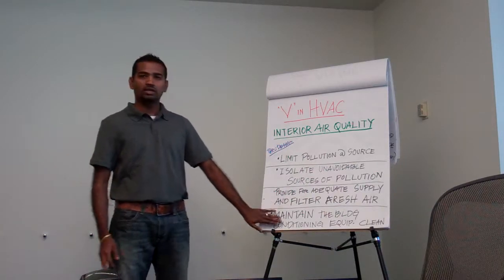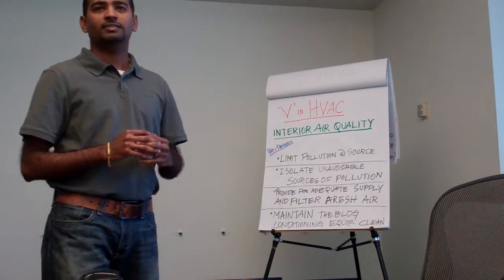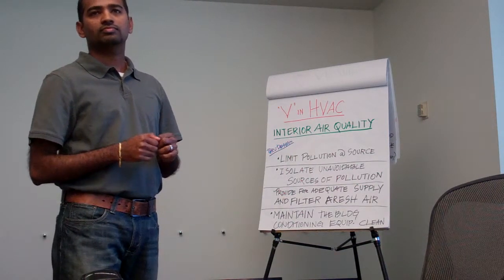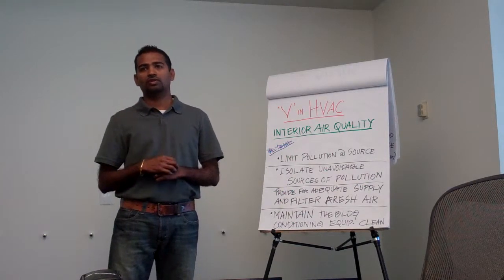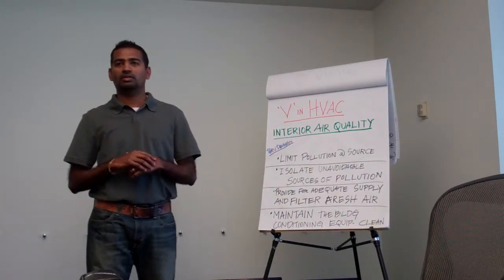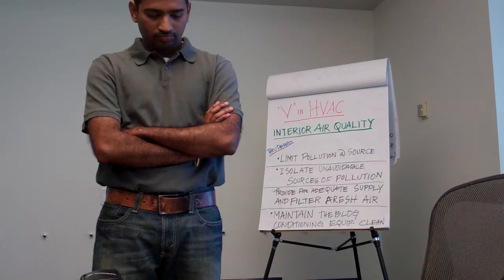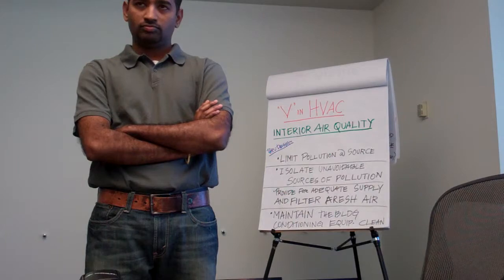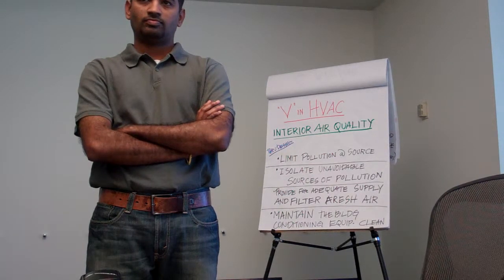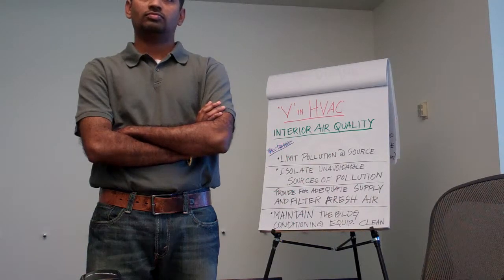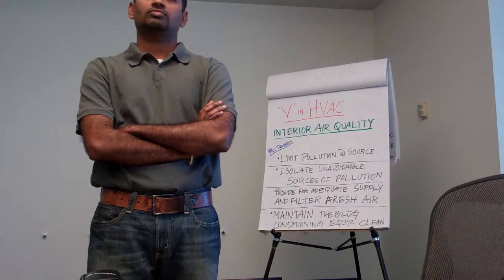So it is important to keep that in mind from an indoor air quality standpoint. Yes, Kelly? On the fresh air portion, isn't there a minimum that's regulated? Yes, a minimum amount of fresh air. Correct, so you can't completely offset that with design. Similar to using the windows for daylighting, you put controls on it to turn the lights off. On the mechanical side, you can put CO2 sensors in to drive down the outdoor air if you don't have a lot of people in your space, down to the minimum that is for the VOCs of the carpet.